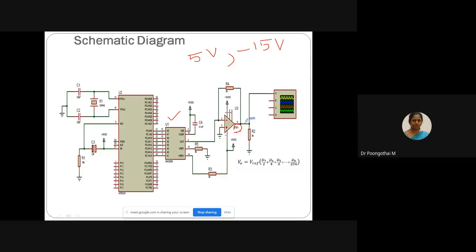So according to this design, for the 8051 microcontroller interfacing, the 8-bit data bus of the DAC is attached with the 8051 on port 2. The 8-bit digital input is loaded into the input lines from A1 to A8 of the DAC. The 8-bit data word range is from 0 to 255, since it is an 8-bit port.